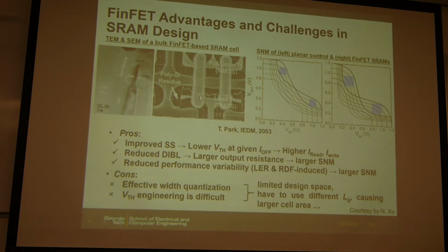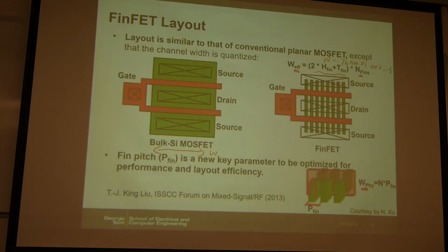So typically for the FinFET, the channel is undoped. You don't dope anything because it's so thin, and because now the gate has better control, you can tune the gate work function to tune the threshold voltage. So you don't dope the channel. And the source and the drain are no longer that thin. So we have the extension area for the source and the drain, so we can dope that area. But for the fin itself, it's typically undoped.